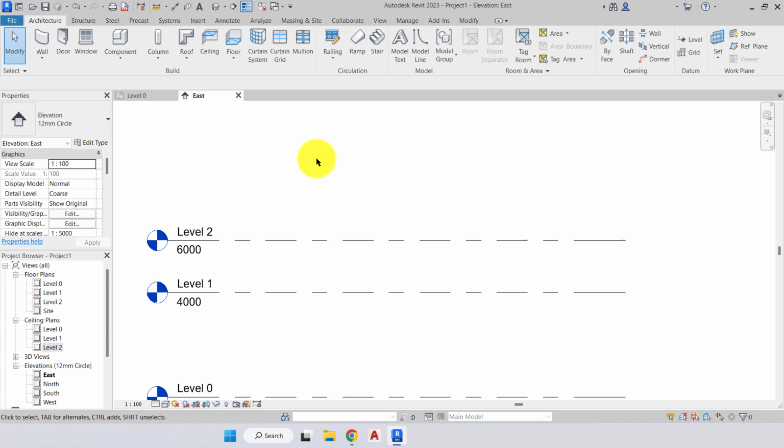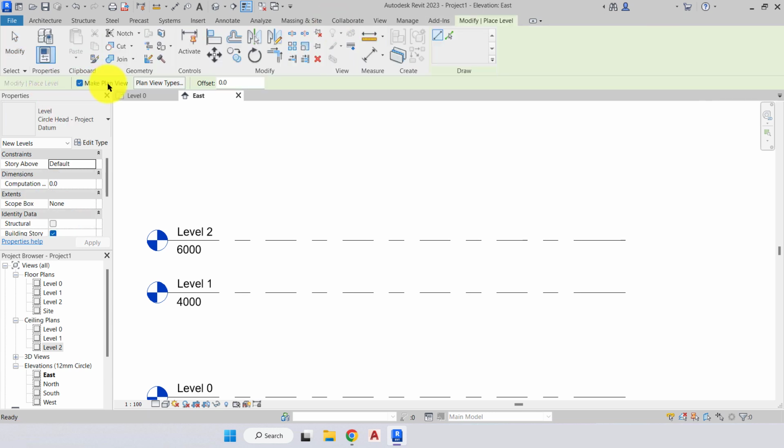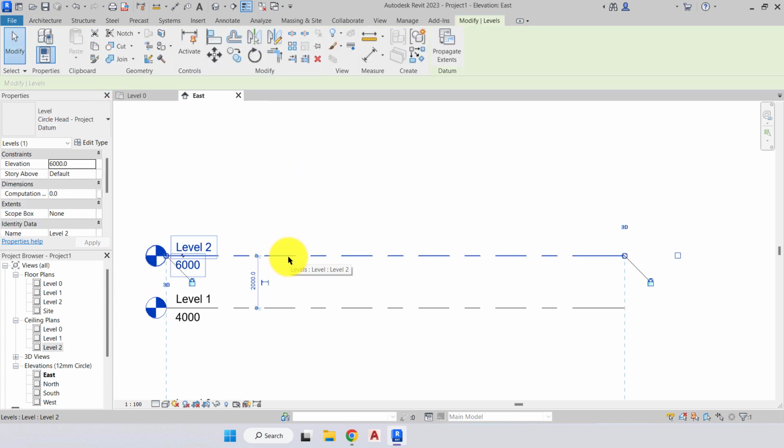So what I want to show you is other ways we can create levels. Instead of going back to the level tool, picking make plan view or not, what we can do, press escape, is we can select our level. And when we do, the modify contextual tab will automatically come up, and we have a create panel here. The tool I want to show you is called create similar. When we use the create similar tool, each new element inherits the family instance parameters defined for the selected element. So all of those active elements that are attached to this level will be copied over.